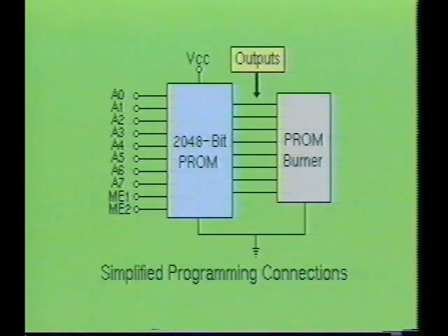As was stated earlier, when the PROM device is manufactured, it contains a high at all addresses. Therefore, the logic lows must be programmed into the device. To program a logic 0, the following procedure is generally followed. First, a voltage of 5 volts must be applied to the VCC input. Next, select the word to be programmed using address inputs A0 to A7.